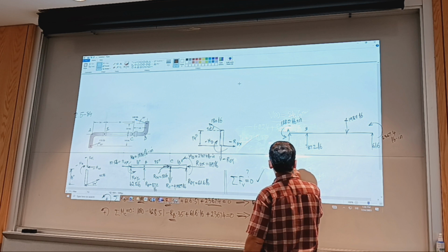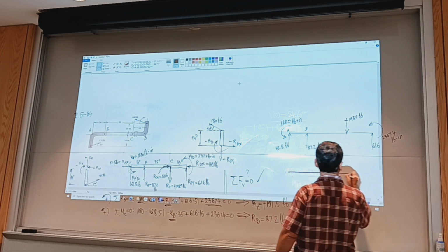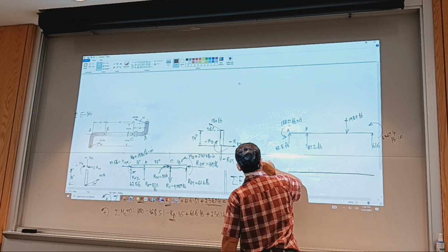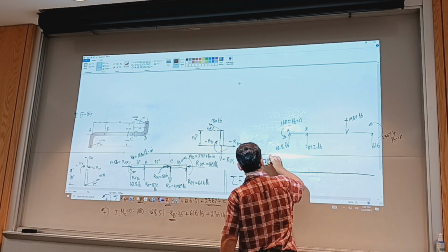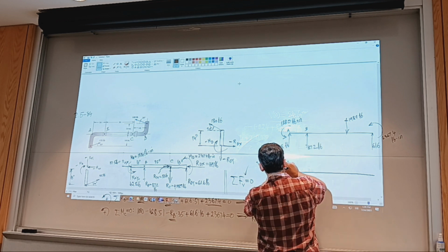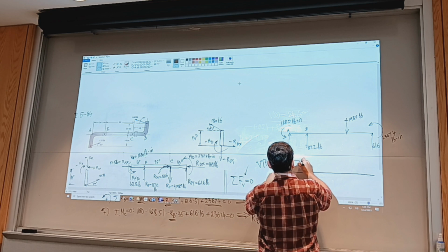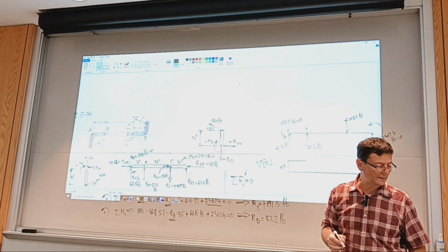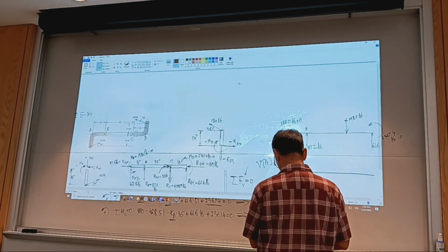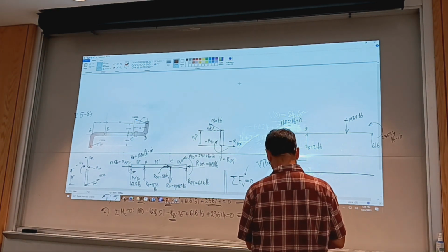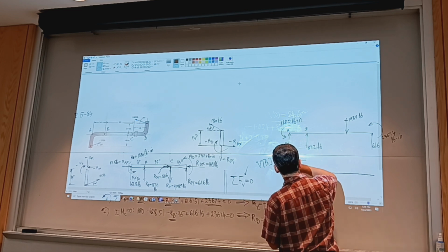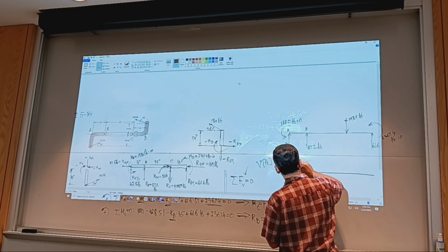All right, let's show the shear diagram, the shearing force diagram. So V, and units are pounds. So I have 42.8, and nothing happens. And then I have a jump from 42.8 by 87.2. So 42.8 plus 87.2 equals 130.